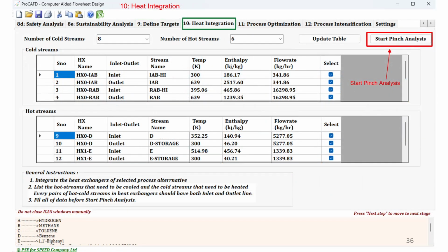In this step, all the input and output stream data related to heat exchangers are passed to this module, which then performs heat integration by the graphical pinch technique. The mathematical programming technique directly linking to the process simulator is also available. See Step 11, slides 38 to 39.